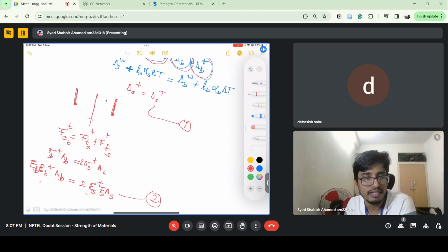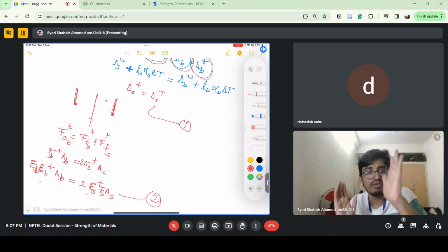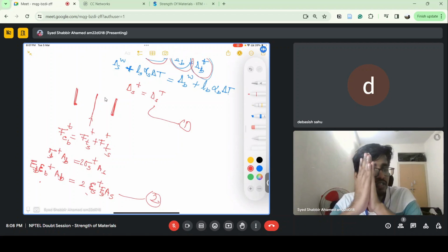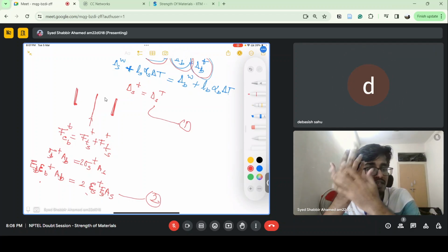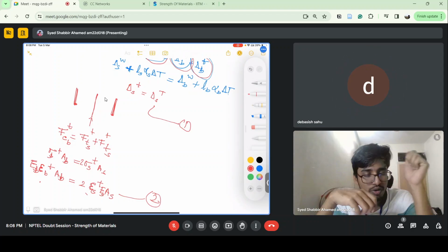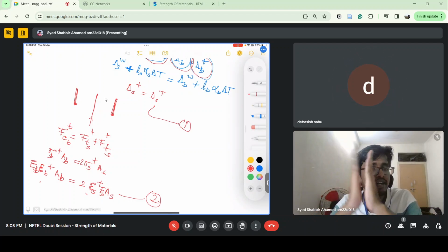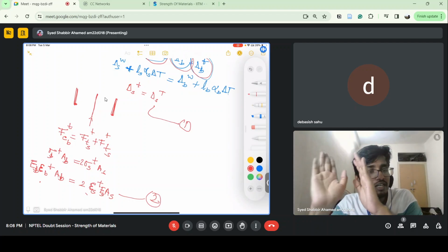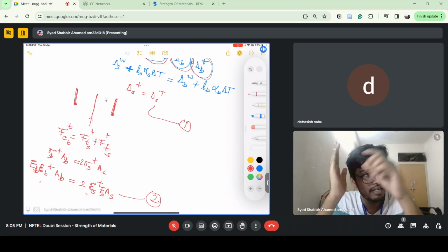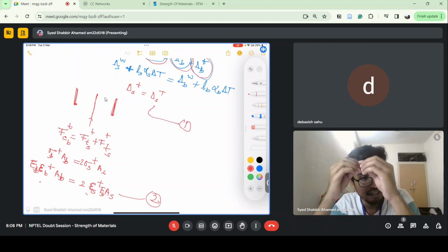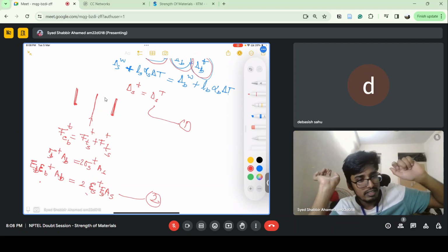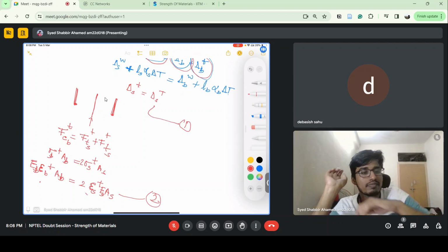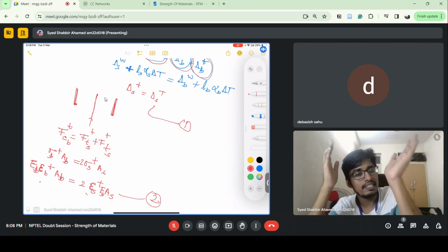Sorry, digital image correlation is conducted for strain. In digital image correlation, we have a sample on which you paint speckles, black dots. After that, you take a lot of images while load is applied. You feed those images to the computer and process them from one time instant to another, as load is increased. The distance between these small dots is calculated, and also the slopes and gradients.